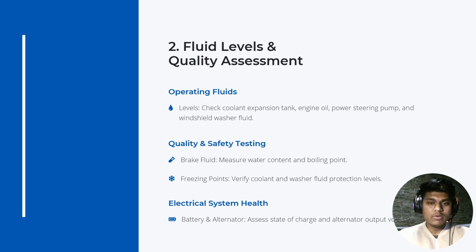Moving to the fluid assessment, we are checking the critical systems for both volume and health. I have inspected the coolant expansion tank, engine oil levels, and the power steering pump to ensure they are within manufacturer specification. Beyond simple levels, we are performing safety tests, specifically measuring the water content and boiling point of the brake fluid to detect any signs of contamination. Additionally, I'm verifying the freezing point protection for both the engine coolant and the windshield washer fluid to ensure the vehicle is prepared for all operating environments.